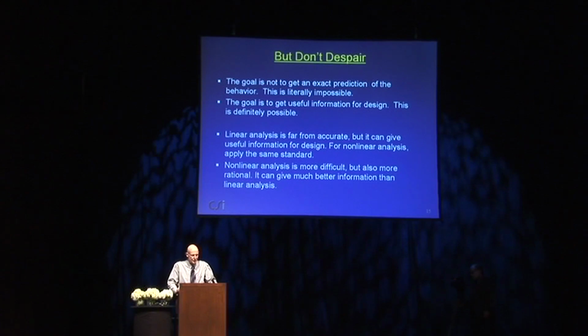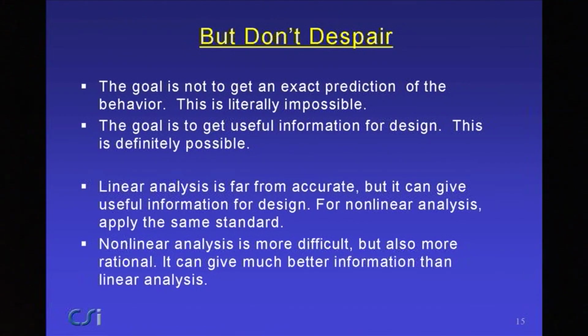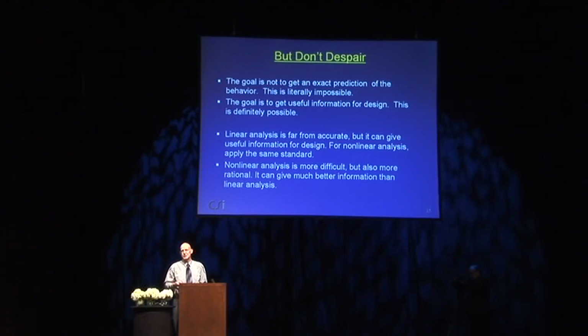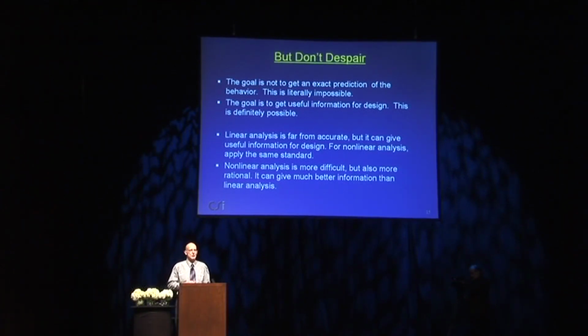But don't despair. The goal here is not to get an exact prediction of the behavior. That, as I've said, is literally impossible. The goal is to get useful information for design, and this is definitely possible. And what I'd point out is that when we use linear analysis to do design, it is far from accurate. If you run a linear analysis and you think you're getting accurate values of stresses and deflections, etc., think again, because you're not. It's by no means accurate, but it does give useful information for design.